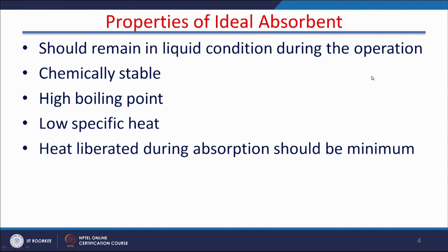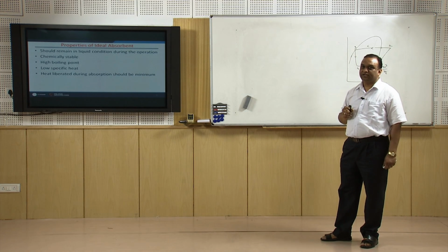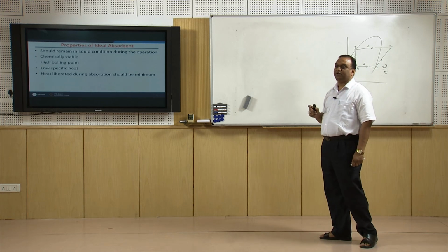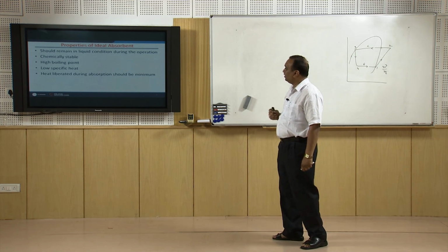It should have high boiling point, low specific heat. Heat liberated during the absorption should be minimum. So during absorption process, the heat liberated should be minimum because this is the heat loss from the system.